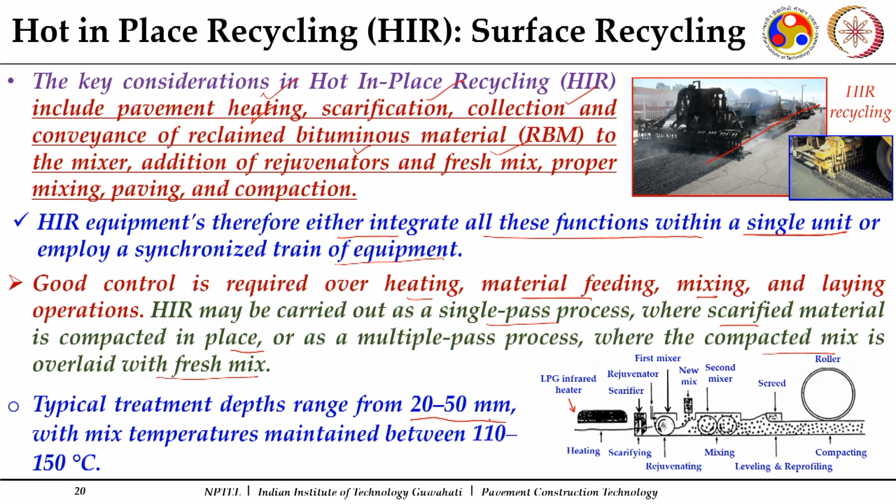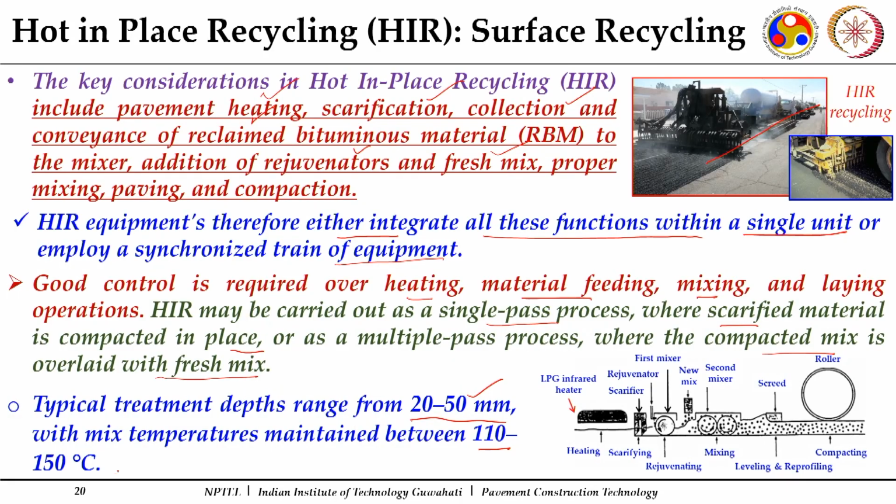Typical treatment depths: because heating has a limitation, hot in place recycling, or hot in situ recycling, is typically done for depths of 1 to 2 inches. So we can consider it is basically restricted to your wearing course or surface courses, and the temperatures usually achieved are in the range of 110 to 150 degrees centigrade.